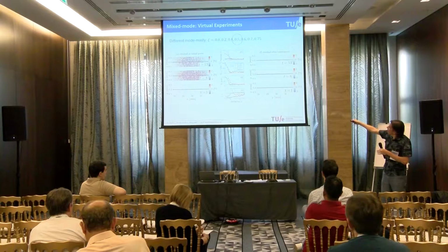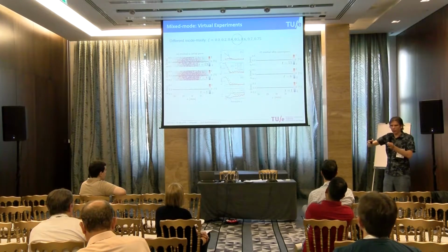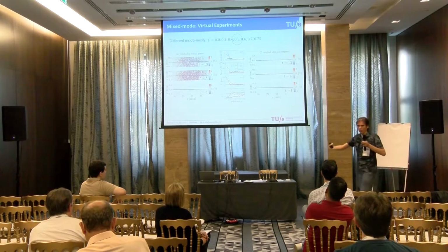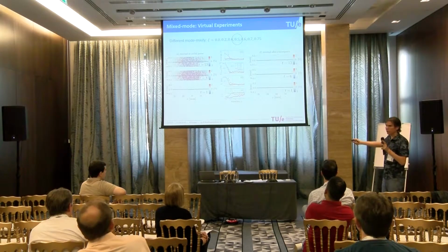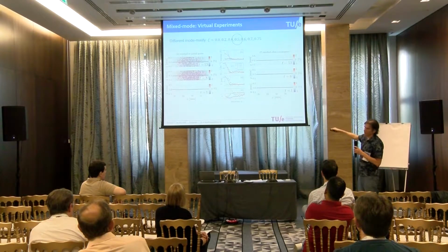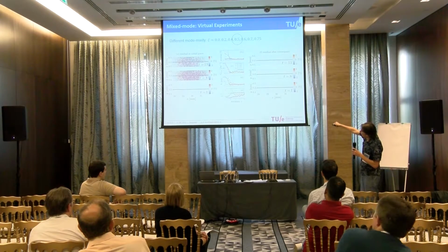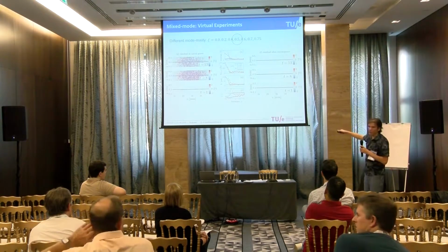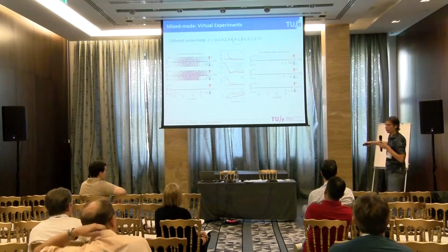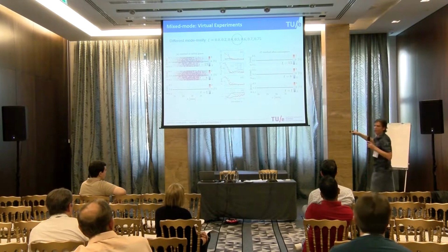Now, if we do this, still virtually, we created a virtual test, and now we're trying to identify the three cohesive zone parameters without using the force. So this is the starting residual fields at different times. You can see that the model is quite off, and in time the residual is going down, and all three parameters are converging. The mixed mode parameter is the least sensitive, and that's what we already predicted beforehand. But then we go to a residual field that's really very nice in the end.